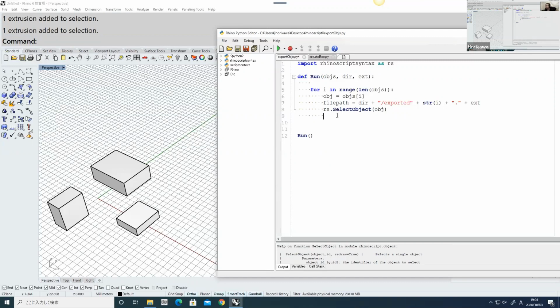Right? Now after we have selected, we can call a RhinoScript function called Command. And inside this command, we can type this export command right here. Now, this is going to be a string, and when you try to call a command using a script, it's better you always use this way. First, this character, then underscore, then dash. So remember those 3 characters. Then Export.